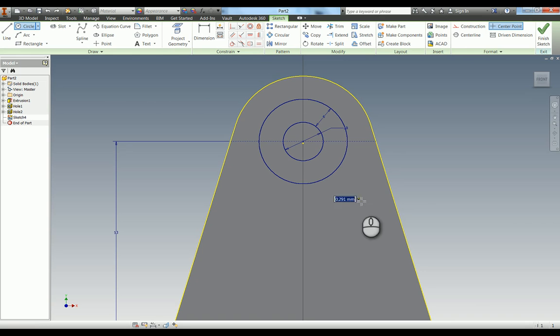And now we need to put in our circles. I'm now going to draw in 2 circles, which will give us the two ends. I'm going to make those equal with each other and give them the dimension of radius 3, so 6mm diameter. I'm also going to vertically align those because we can see that from the drawing, and we do have a dimension between them, which is 11mm.